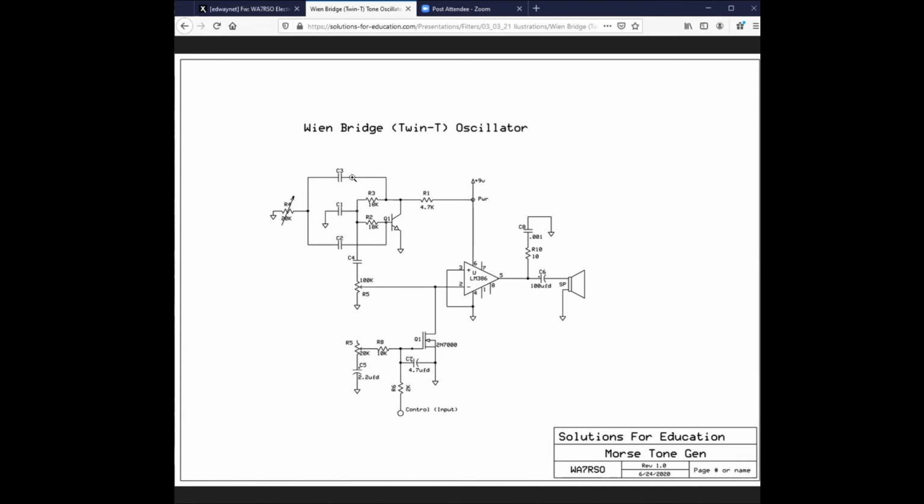They depend on the value. So there are RC calculations to determine the resistance and capacitance of this here for getting you the right tones. Remember, you have a high pass filter and a low pass filter. You put them together with the right frequencies, and you've got yourself a band pass filter. So what you've got here is an oscillator, which is really nothing more than an amplifier operating with feedback, and the feedback is what makes an amplifier an oscillator. That's something we always want to keep in mind. An oscillator is nothing more than an amplifier with positive feedback.